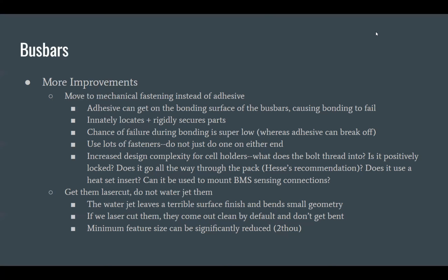Laser cutting is awesome. It applies no force. It has a way better surface finish, and it's super fast and super easy. Just don't water jet them. The water jet applies a lot of force. It bends them. It causes bad surface finishes, and it gets dirt all over your bus bars. Just use the laser.